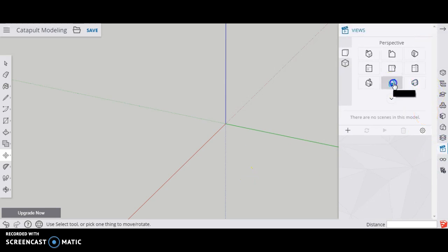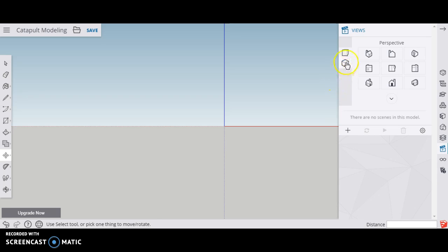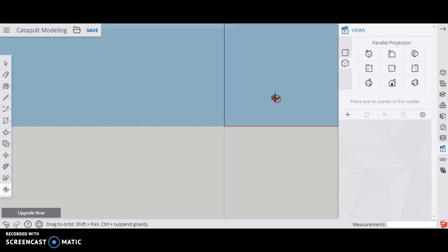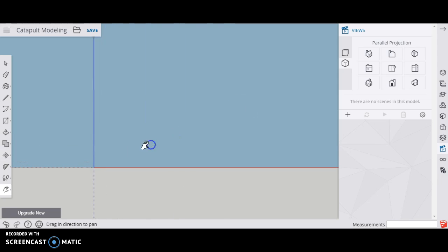I'm going to go to my view and take a front view with a parallel projection. So I'm working on a really flat plane here. And now, again, I could use the rectangle tool. This time I'm going to make a rectangle 11.5 by, or maybe it's 3/16 is first, I'm not even sure. I could also use my line tool. 3/16 tall by 11.5 inches.